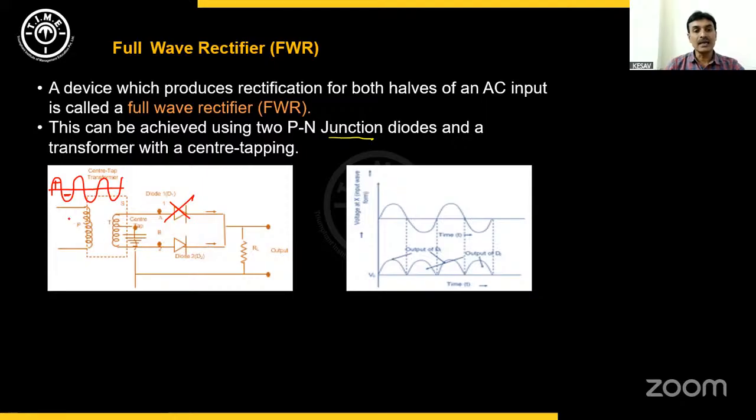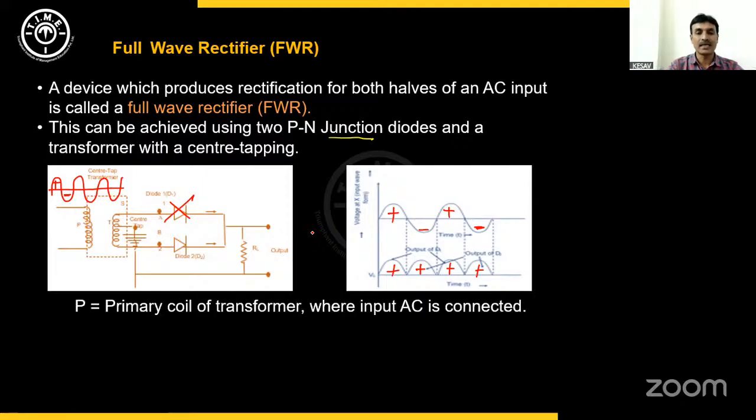Anyway, that half cycle is also passed. So positive half cycle that comes here, and this negative half cycle is passed by the second diode as it acts as forward bias mode. So that is also passed. Okay, the negative half cycle. Again, positive half cycle comes over here, and this negative half cycle also comes into existence in output. Understood? That's how this full wave rectifier works.